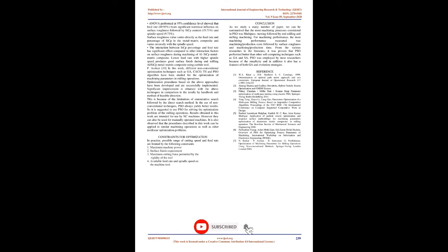Devarasetty Devaraj [9]: In this paper, a fuzzy logic-based model is developed for surface roughness prediction during end milling of Al/SiCp metal matrix composites. Predictive capability of the developed fuzzy rule-based surface roughness model is verified with experimental work, with a mean error of 4.56% and a mean squared error of 0.073. ANOVA performed at 95% confidence level showed that feed rate, 69.93%, bears significant statistical influence on surface roughness, followed by SiCp content, 19.71%, and spindle speed, 9.73%.